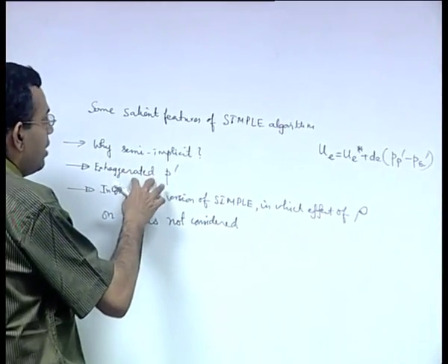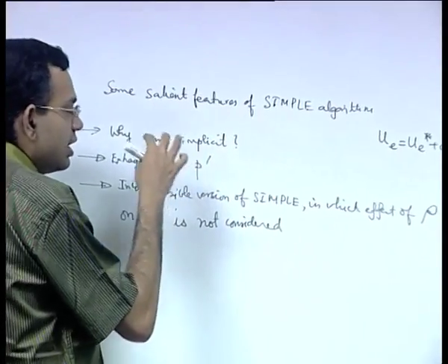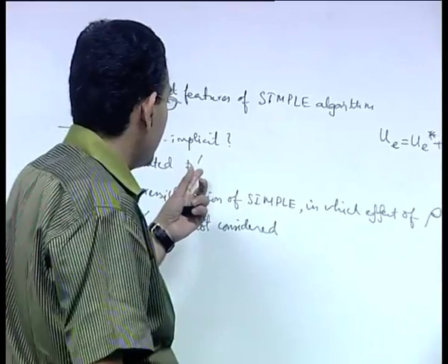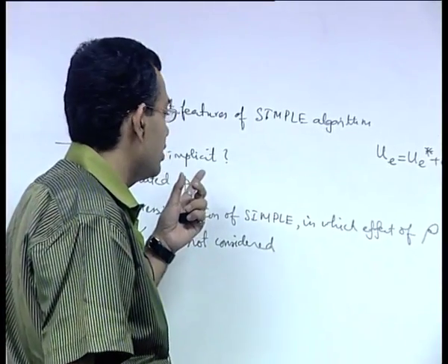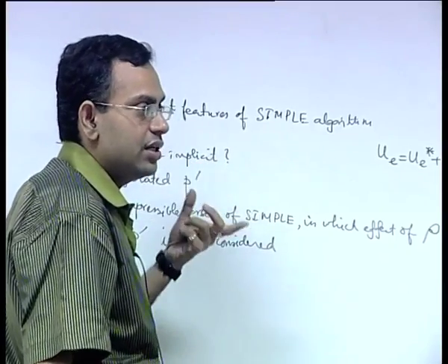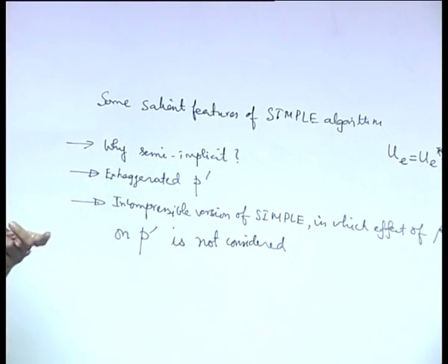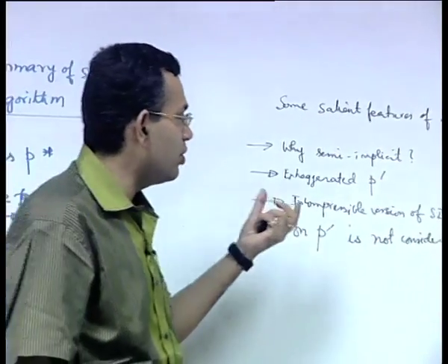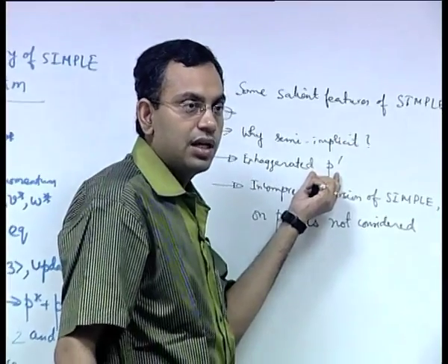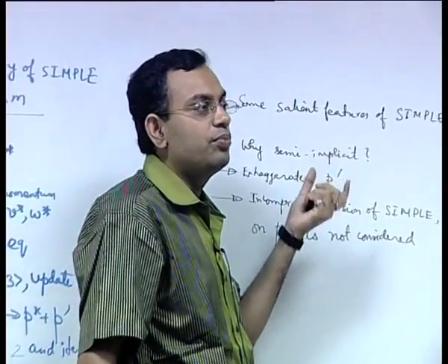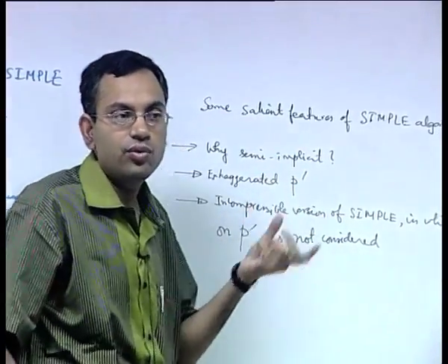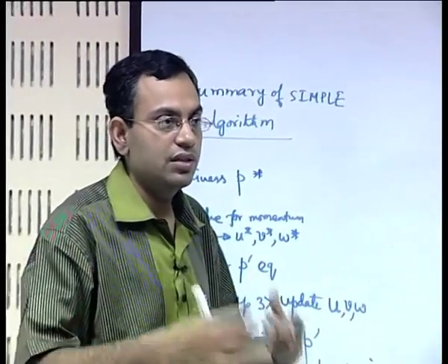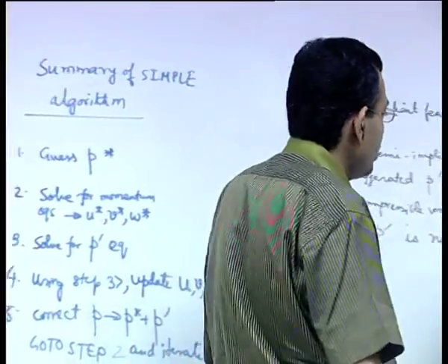Now when we have an exaggerated pressure correction, what it does is something as follows. When it has an exaggerated pressure correction, the new value of pressure which is predicted on the basis of the pressure correction is always exaggerated from the value that you would have expected. Whatever value of pressure that you would have expected, the correction is more severe to take it away from that. So, how would you bring the pressure back to a non exaggerated corrected value? So, that you can do in certain ways.